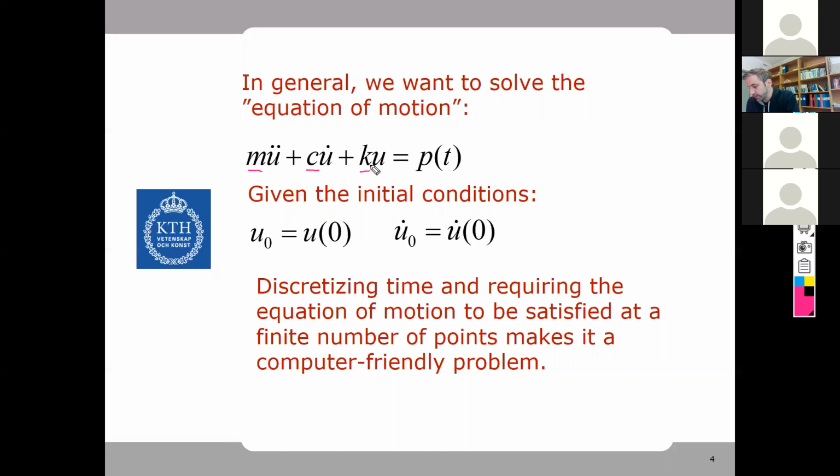And then we have the stiffness, of course, times the displacement, and it works like any idealized spring, which produces a restoring force proportional to the displacement. And these are known as the forces internal to the structure. And this has to be equal to the forces external to the structure, which are symbolized here by P, which are the loads that are affecting the structure.